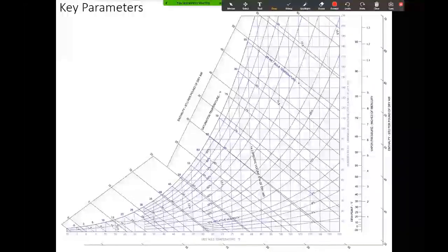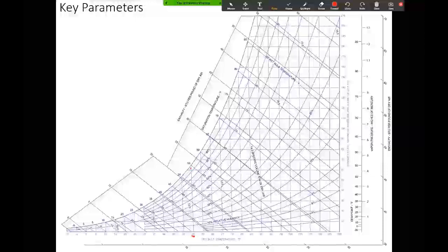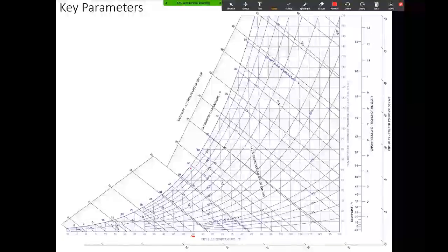So this is a typical scenario that you're going to see in commercial HVAC systems. You supply air to a space that's typically about 55 degrees Fahrenheit, and it's going to be at 95% relative humidity. So somewhere in there. So when we supply 55 degree Fahrenheit air, 95% relative humidity. Remember, this is dry bulb. We're feeding air into rooms where there are people.